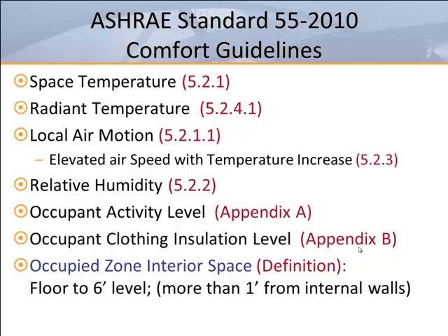The zone of interest or occupied zone is defined by ASHRAE 55 as from the floor level to 6 foot above the floor, and more than 1 foot from internal walls, and 3.3 feet, or 1 meter, from outside walls, windows, or fixed HVAC equipment.